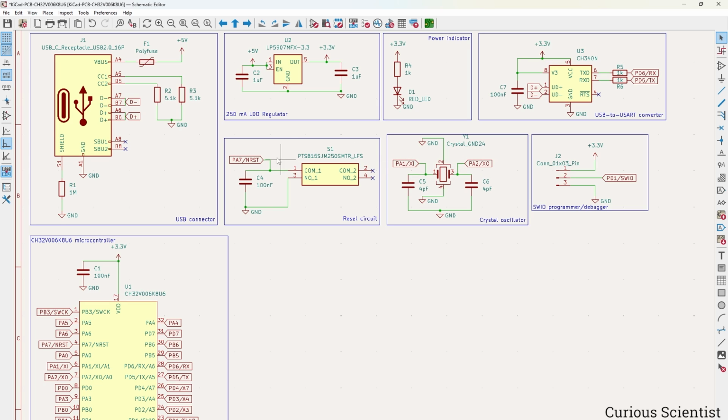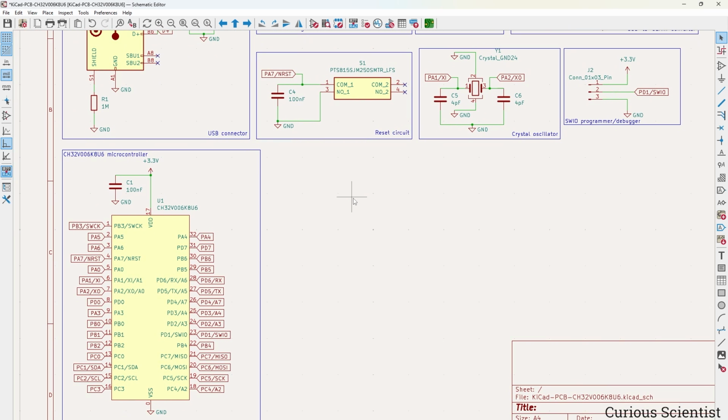And then one more pin that I'm not going to break out is the reset. So that gives us 27 pins total, which we have to place somewhere. And then what we are going to do is that we want to have 3 volt available, 5 volt available, and ground available on these pins. So we get back from 27 to 30. So then with those 30 pins, we can split them into 2.